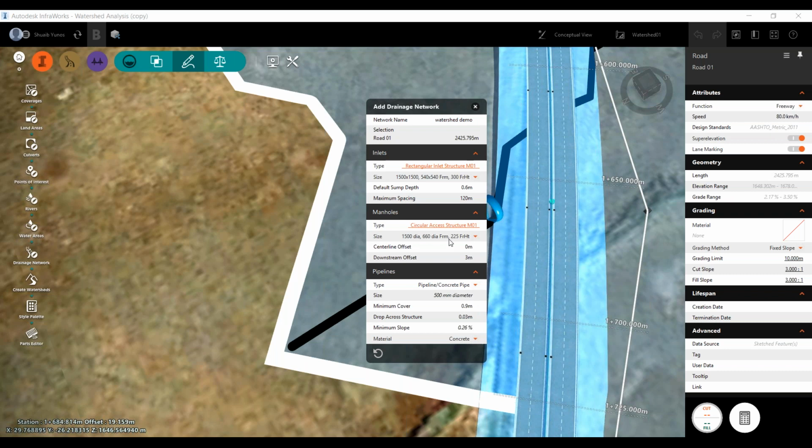If you're using this, once you make any changes, don't click enter, because once you click enter, it will go automatically to size the inlet. You just click somewhere else on the asset card. So please don't click enter. So once I edit this, don't click enter, click maybe somewhere there, and then it'll go off. Because once you hit enter, it's going to take you into and do something else, right?